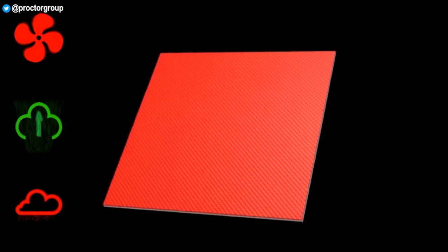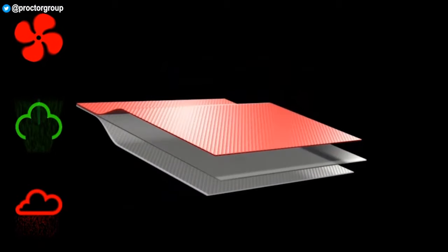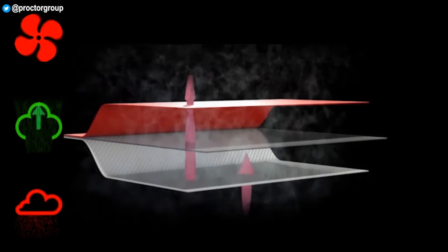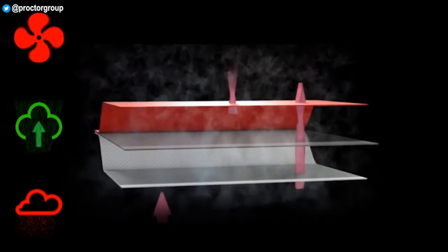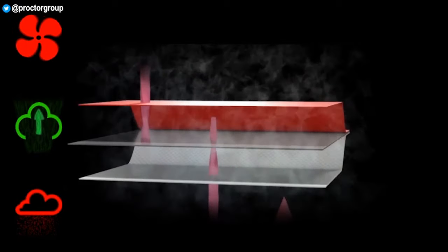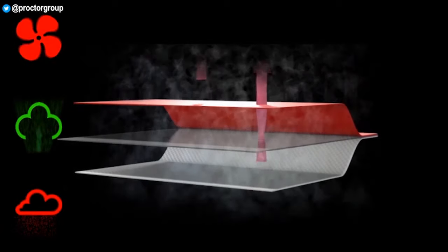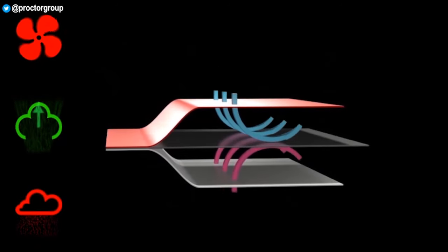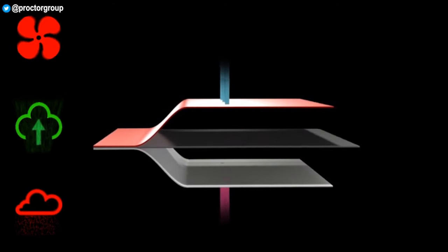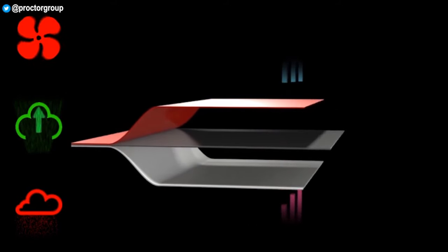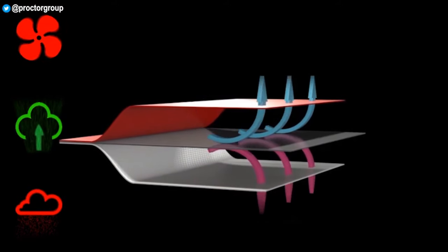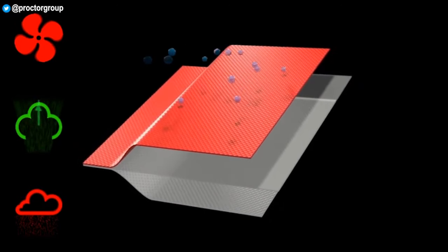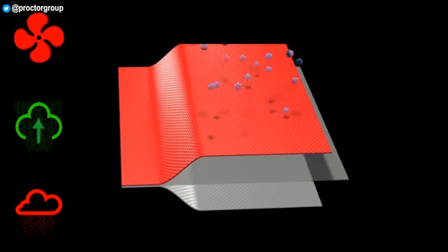Airtight vapour permeable membranes. Film laminate membranes use a film core layer in place of the melt-blown fibres. This film is sandwiched between carrier layers, which are typically similar to those used in SMS membranes. As before, these outer layers help provide additional water resistance, while also protecting the core from physical damage. This film allows moisture vapour to pass through, but provides a barrier to both liquid water and air. The water holdout properties of this film core mean that these membranes typically offer higher levels of water resistance than air permeable materials. However, this comes at the expense of a greatly reduced vapour permeability.